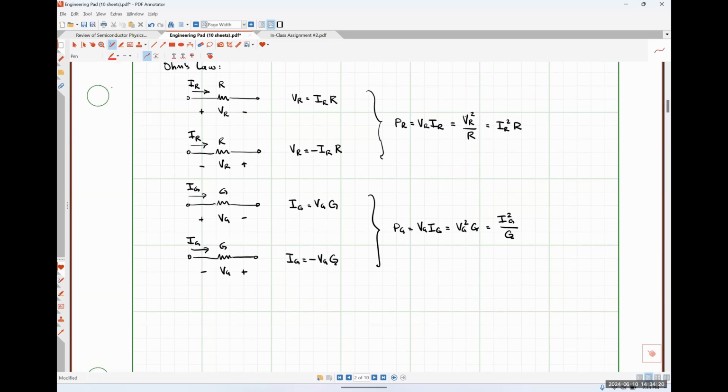Before we move on, I just want to make a suggestion to you guys, just for your next couple of homework assignments and all of that kind of stuff. It might be in your best interest to have this information that I've boxed in right here handy in front of you whenever you're doing any of your circuit analysis, just to remind you that anytime you see a current flowing into the positive polarity terminal, give Ohm's law a plus sign, and anytime you see a current flowing into a negative polarity terminal, to give Ohm's law a minus sign.